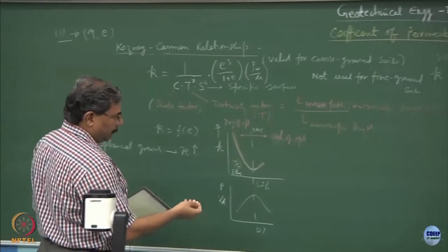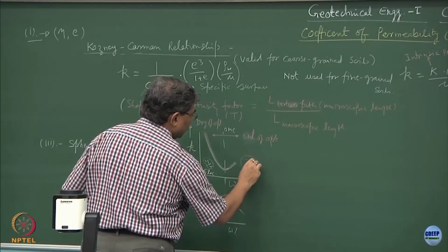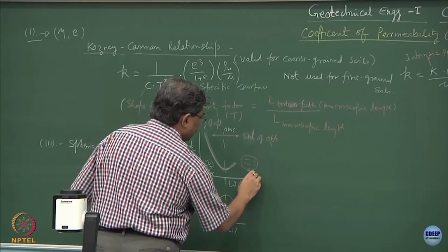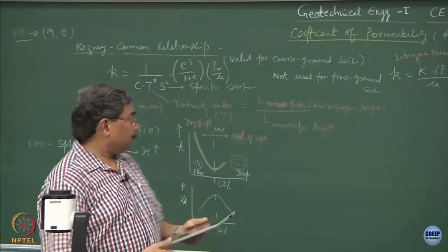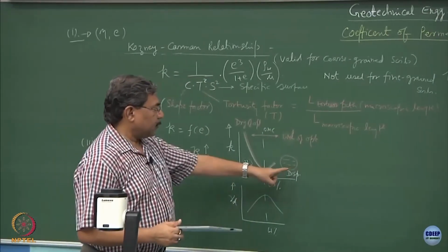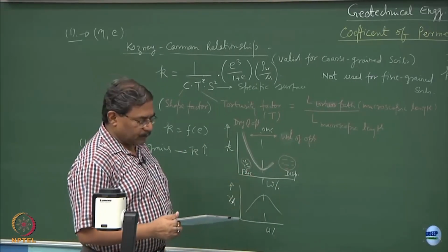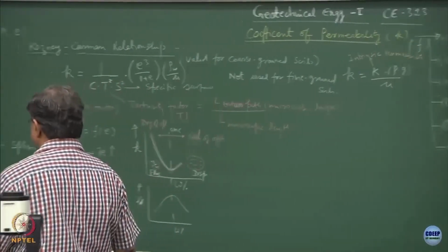And on the wet of optimum we have the particles which are more dispersed. So, by definition or by fundamental nature, a dispersed structure shows less hydraulic conductivity as compared to the flocculated structure. Then we talk about the formation also.